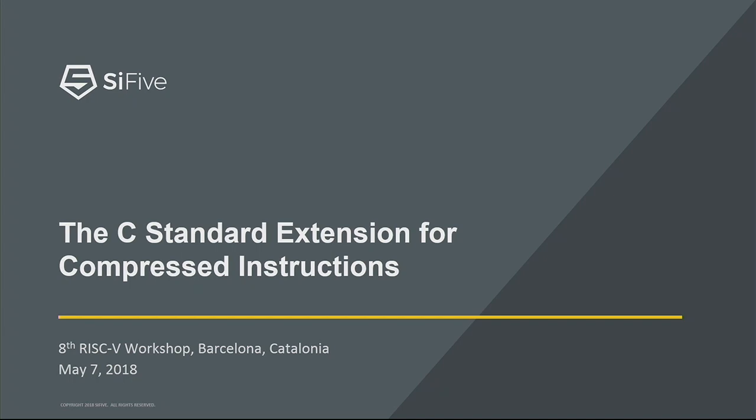All right, so I'm going to talk briefly about one last ISA extension. The compressed ISA extension is there to cope with the fact that although the base RISC-V ISA encoding is nice, it's elegant, it's very regular, 32-bit RISC ISAs just don't produce very good code density.